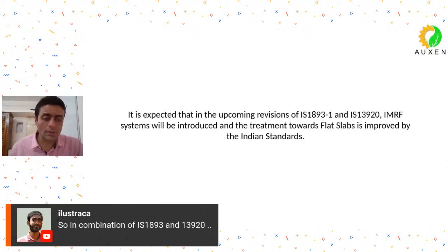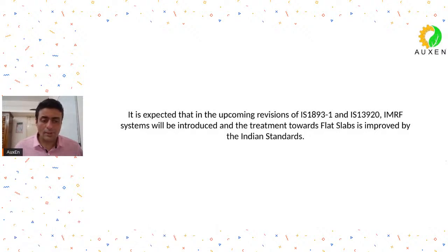Oh, sorry, 13920. My mistake. I should have said that. When you look at IS 13920, when it is calculating the design shear, or the shear due to ductility effects, we calculate it as per the probable moment capacity approach. There is a factor of 1.4. That 1.4 factor has, I would say, inbuilt effects of the overstrength and some amount of redundancy, but it's an indirect approach that is followed. Yes, good. So this is what I had to tell you.